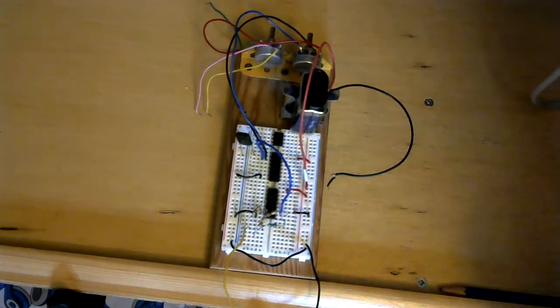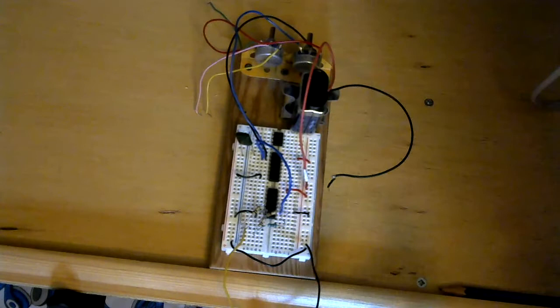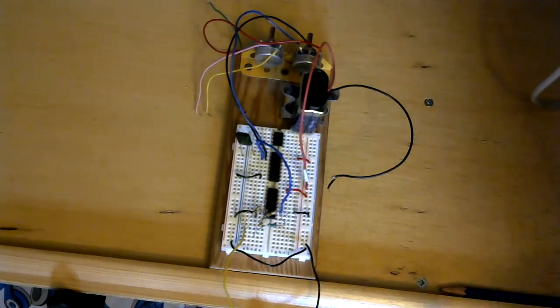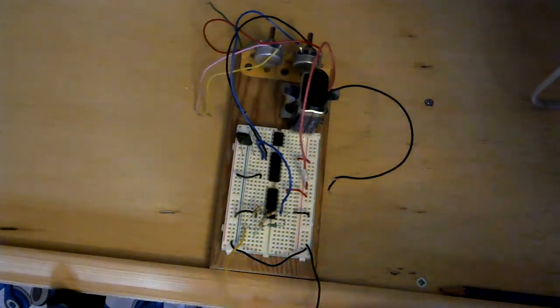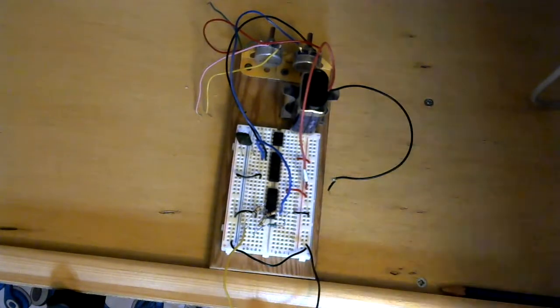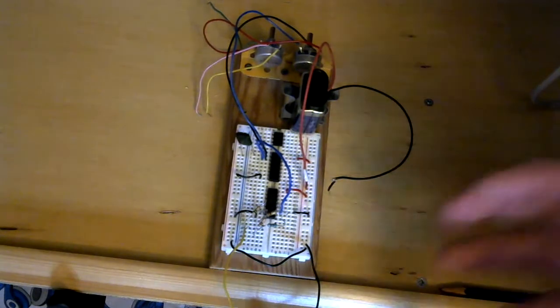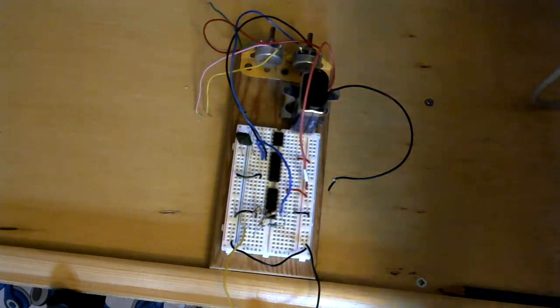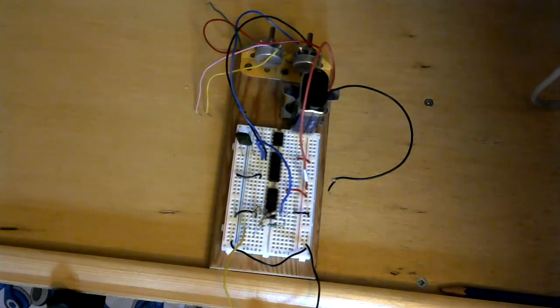So that's the theory proved, that if I take a square wave oscillator as my clock input, put it into my clock input on the 4040 counter, and then take the binary counter registers out one by one, I can start adding sub-octaves. So that was the theory proved. So now the thing to do was to take that and put it into a panel on my modular synth. So let's go and have a look at how I did that.